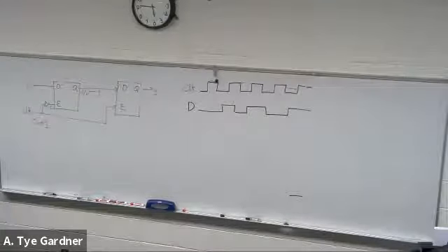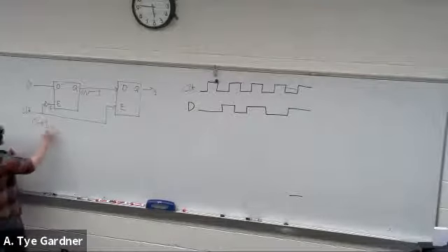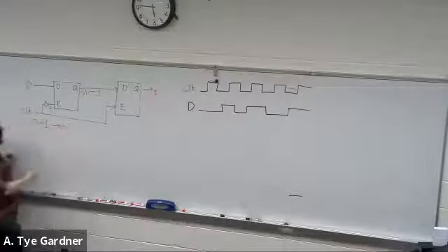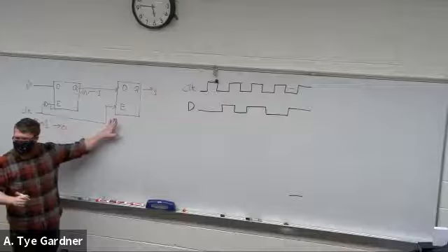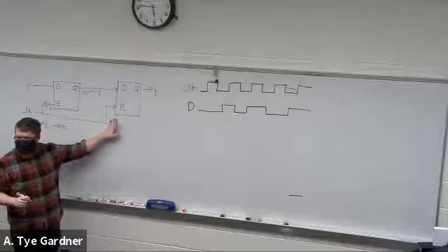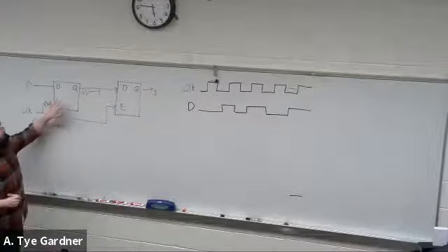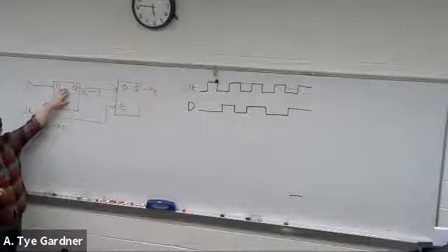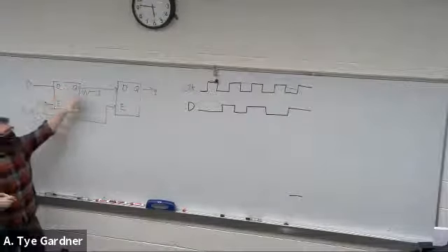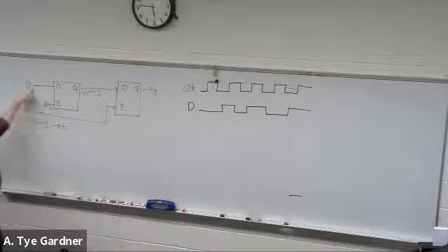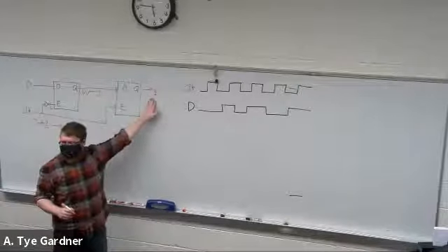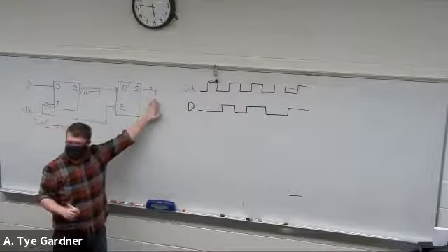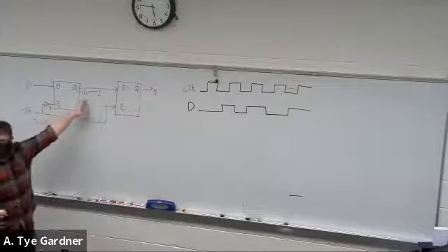Pass that 1 through. So, let's continue on for just 1 second. Now if I flow back to 0, well, this turns off, right? And we've kind of talked about it, that there's a little bit of delay here. So this hasn't had a chance to do any of the wiggling that the D would do. So this 1 is now locked to that Q. We're still 1 here, regardless of what this wire is doing, because we're not enabled.